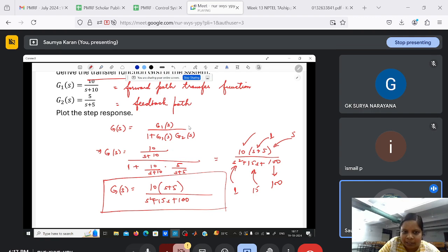Num is the variable that stores the numerator coefficients in the form of an array. Denominator also stores the coefficients of the denominator terms in form of an array. Now we create a transfer function. TF is an inbuilt function that can be called to make a transfer function out of numerator and denominator.